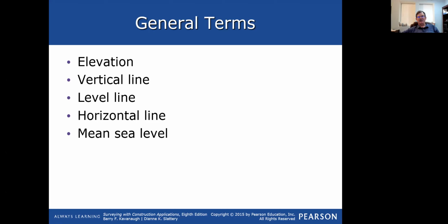There are various reasons why, and I'm not going to get into them for this class, but I do remember sometime in the 80s, the federal government ran trigonometric and actual levels with a level gun like we're going to look at. They ran from the Atlantic Ocean to the Pacific Ocean, and everything they did to check in between showed the ocean was not level. So mean sea level is something we've gotten away from a little bit now.